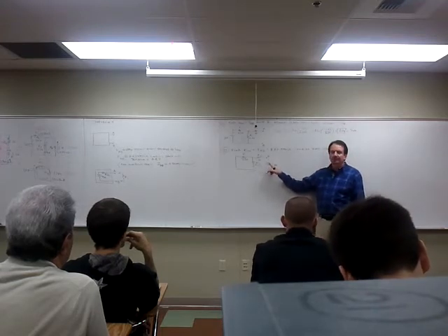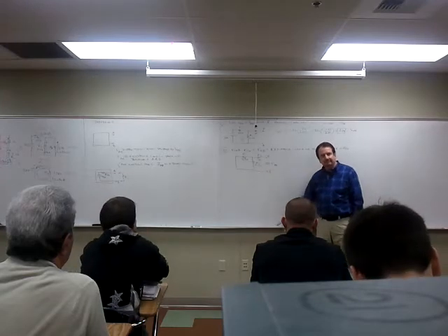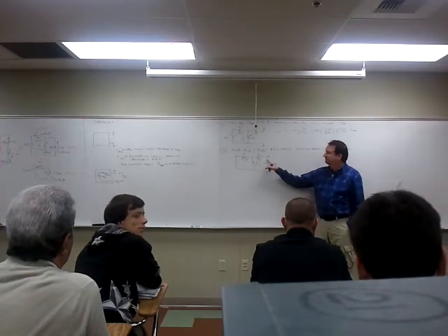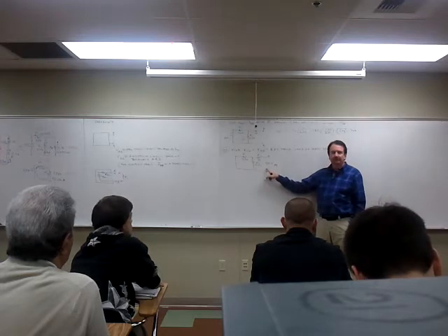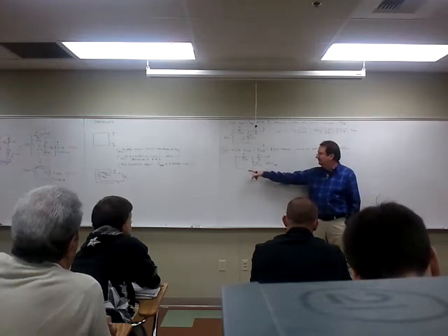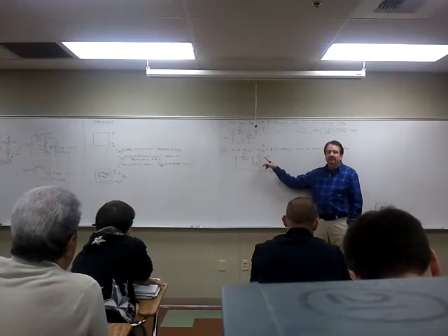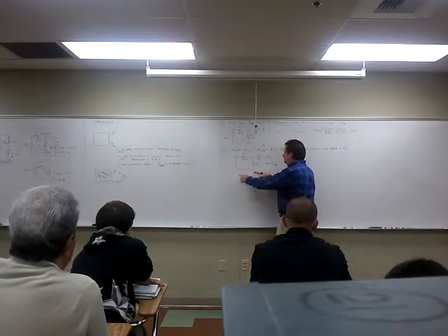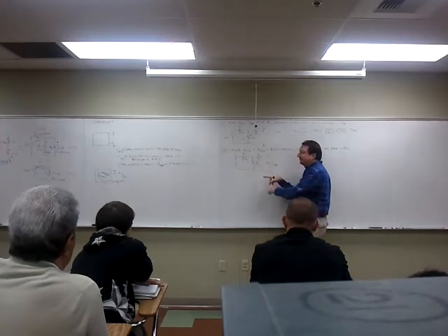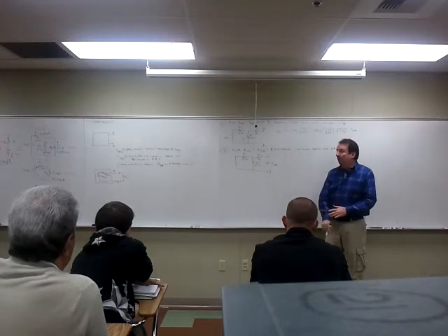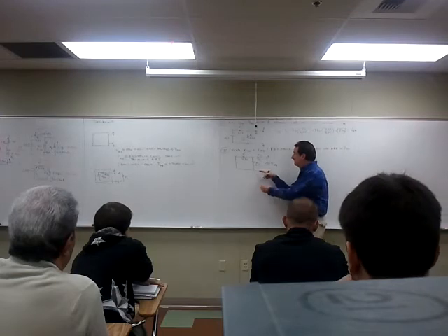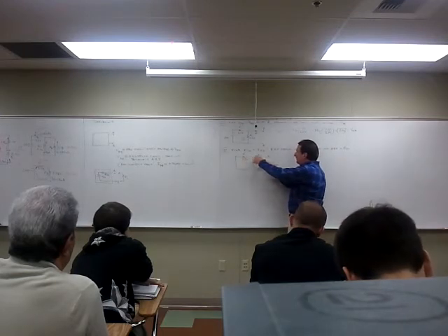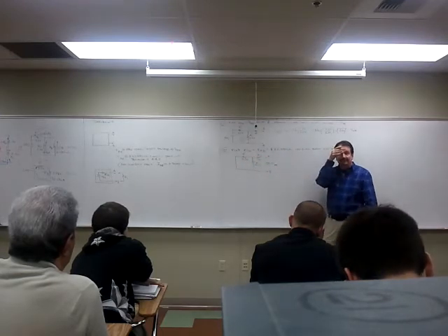If you put a source of voltage here, would the source of voltage cause current to flow? So current would leave here, split two ways, then go through resistor 3. So from the point of view of a source here, doesn't current leave, split amongst R1 and R2, then all flow back through R3?